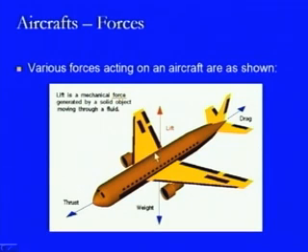Then there is another force, a propulsive force, generated by the thrust at the back if it is a jet engine, or otherwise, if it is a propeller engine, it is sucking the air on this side and pushing the aircraft in the forward direction. That is why there is a thrust with which this aircraft keeps on moving forward. So, this acts in the x axis direction, longitudinally, in the forward direction.